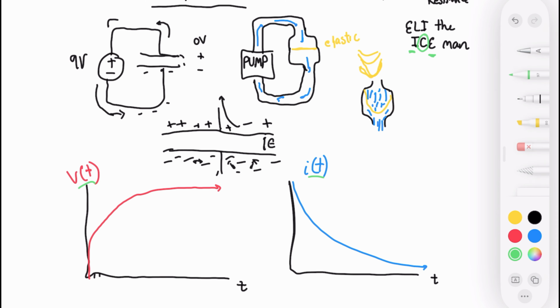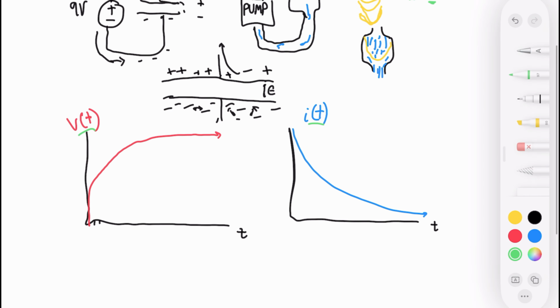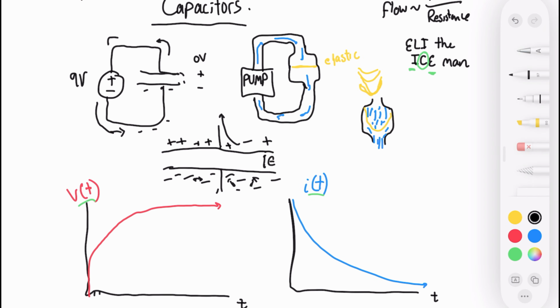And there's a really nice, nifty way to talk about the relationship with these that we see in a capacitor, and it goes like this. Your current as a function of time is equal to your capacitance times the derivative, or the rate of change, of your voltage. And this should intuitively make sense. Basically what happens is, of course, current is related to the movements of electrons.